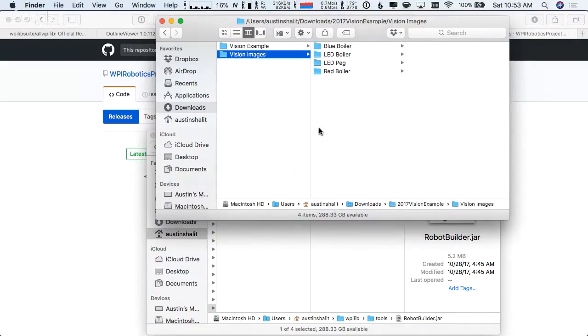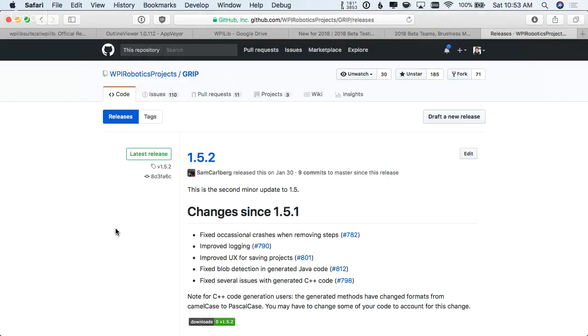And you can use GRIP, or you can write the stuff by hand, and you can get the vision stuff working. And then when you finally get your stuff all together and it's working, then you just have to tweak it a little bit for your camera and the color of the light, like whatever. But you now have tested it with hundreds of images. So you try an image, see if it works, and you go, oh, it's working, it's great. Then you go to the next image, and maybe that one's working. You go to the next image, and maybe that one's not working. So you tweak some of the parameters on a filter, and you go back and try them again. And you just keep doing it until you can see all the images you care about, that it recognizes.